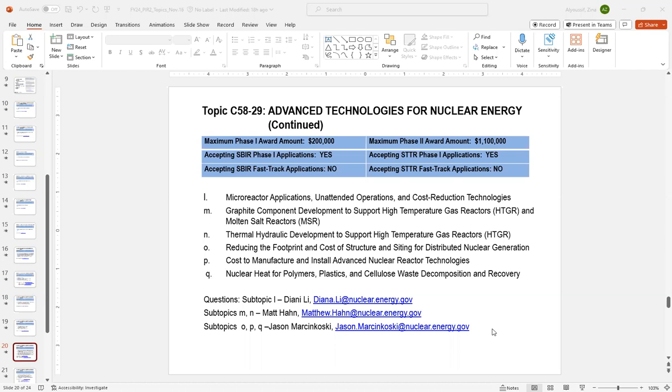Yes, they're quite large. I think we're mainly talking about the reflector components, for example, in a pebble bed reactor. And you could reference the X Energy and Kairos licensing submittals. They contain some information that can give you an idea as to the size. And they are certainly hot. They're reactor core components. And I would reference those submittals as well as some of the NGNP reports from Idaho National Lab over the years that talk about some of the sizes and temperature ranges that are relevant to gas-cooled reactors.